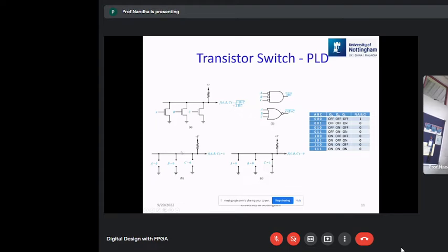If all three gates are given zero value, like what you see here, then the output will be at 1 because this offers a high output impedance. If any one of them, for example here C, is connected to 1, then the output becomes 0. So you can see that this logic is a NOR gate. The entire truth table is given to you here, for different values of ABC.